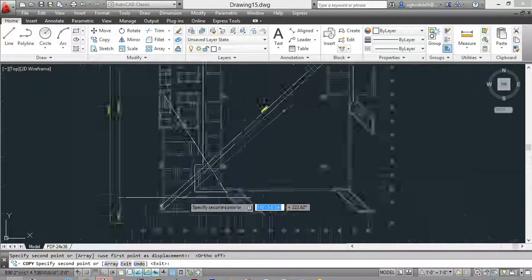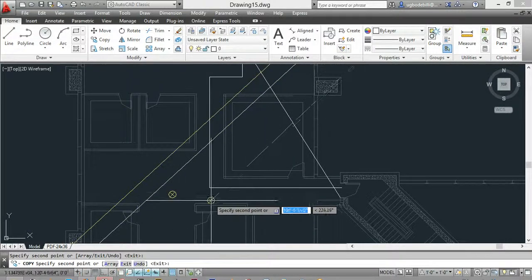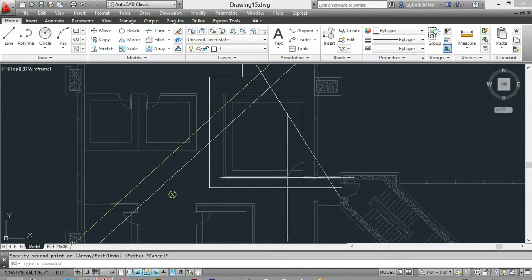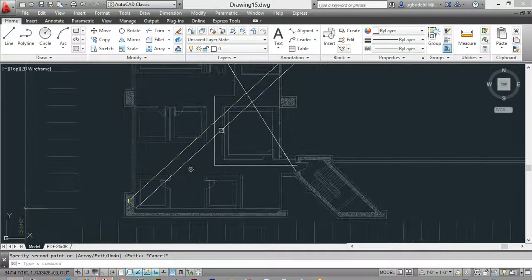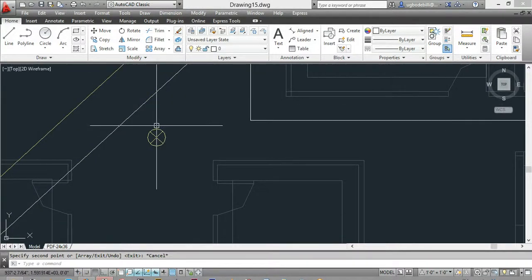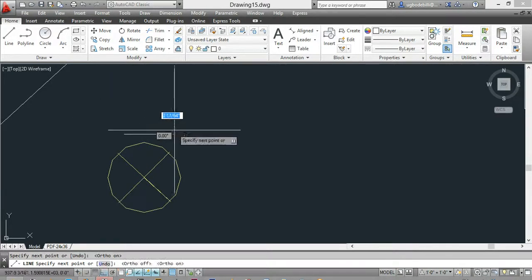Also, as an example, once you get here, you see an exit sign telling you to go this way to these stairs. So for the exit signs, you sort of have to think about and determine what makes sense depending on someone exiting from this room and looking in this direction and just knowing which way to go. So to delineate which way to go, you'd have an arrow over the top of the exit sign telling people which way to go.